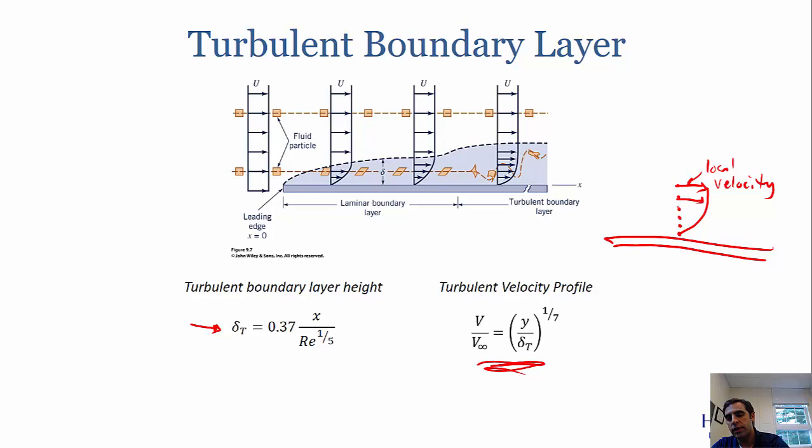We're going to measure that the velocity is higher the further away from the plate we go, and slower the closer to the plate we are. We're going to compare that velocity profile that we get experimentally to what's expected for laminar and turbulent flow, and try to figure out what the critical Reynolds number is for our plate.